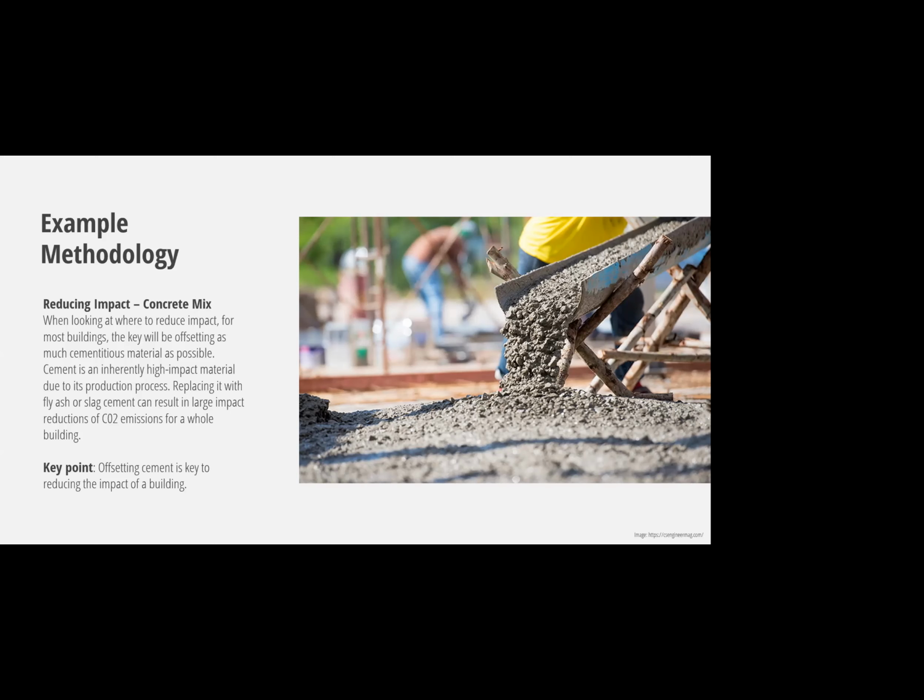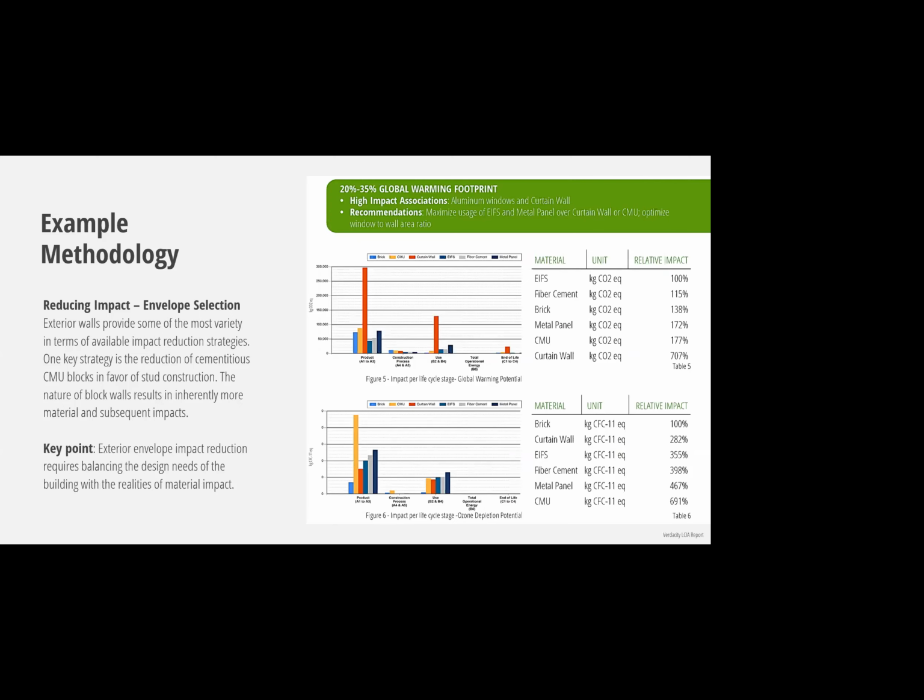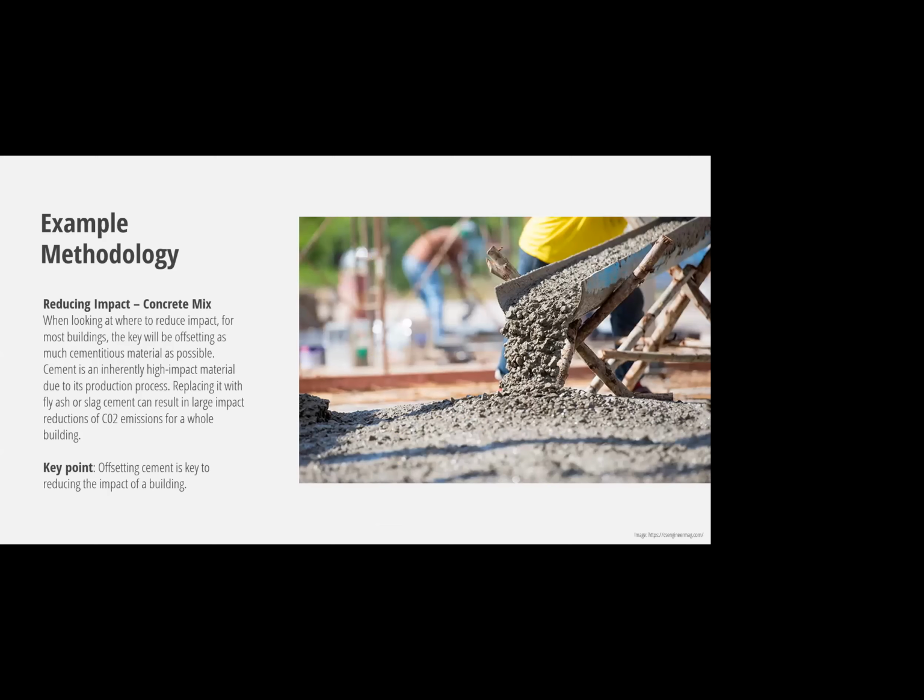What we've seen a lot is that fly ash does provide multiple performance benefits over a standard concrete mix, particularly in foundation applications. But it does require some specialty to work with. So you need a team that understands that if you're specifying a high fly ash content, you need to understand the different drying times and how things are going to affect the schedule, so that you don't reduce the efficiency of the building overall. Just by using fly ash, you'll start to see reductions in the building footprint, due to the sheer proportion that foundations make up.